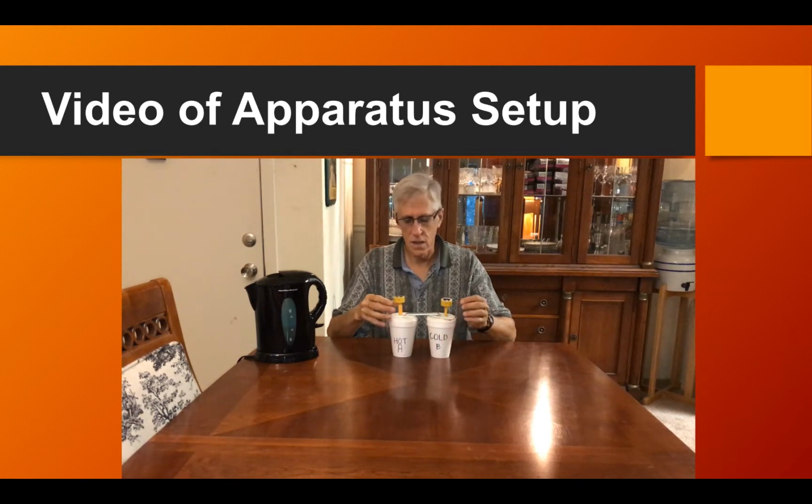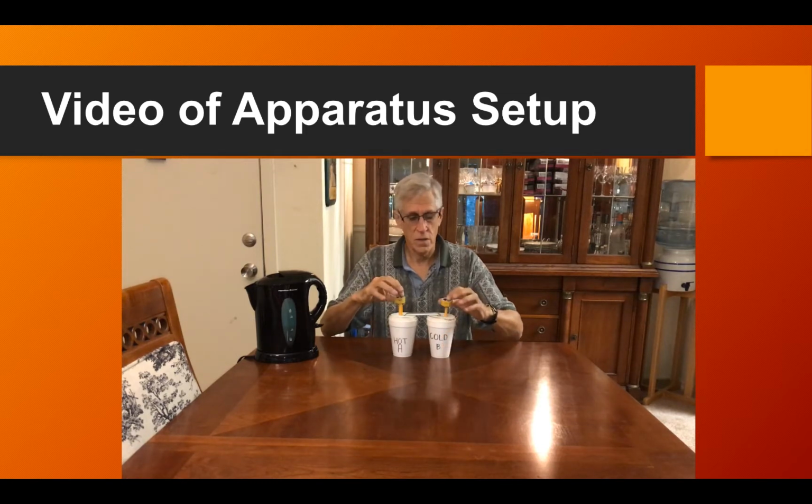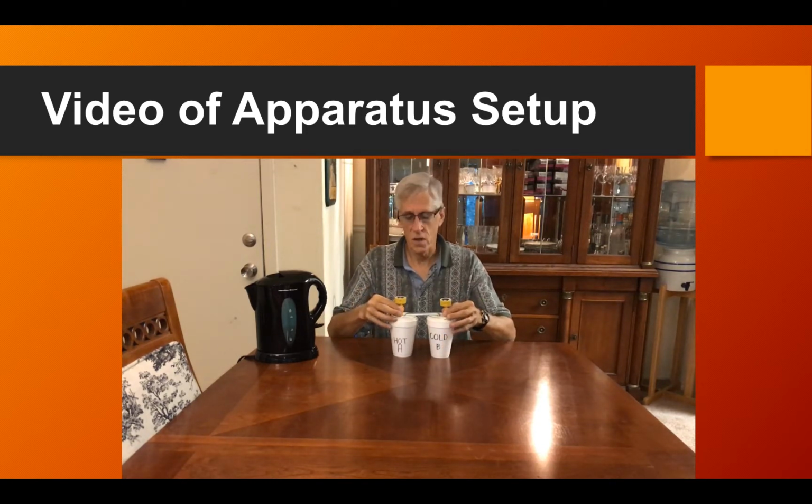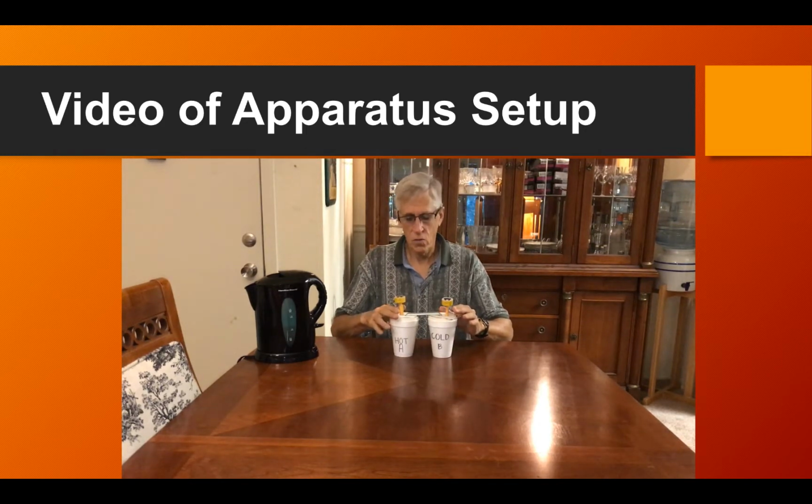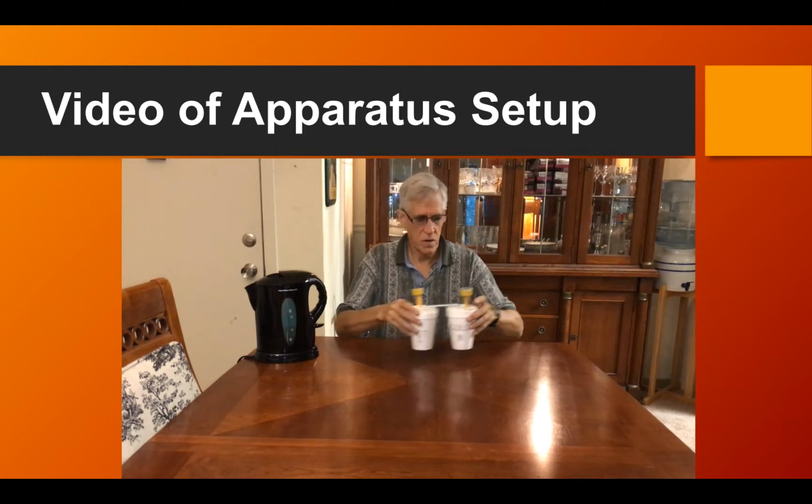And then the second thing is to make sure that they're reading in Celsius. The button on the right hand side of each thermometer switches between Celsius and Fahrenheit. They should be delivered to you turned on in Celsius mode, but if they're not, just take care of that yourselves at your station. So this is going to be used for experiment A. Experiment number 1 is going to be hot water in A and cold water or tap water in B.